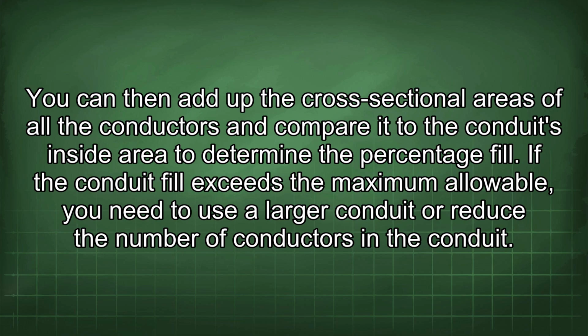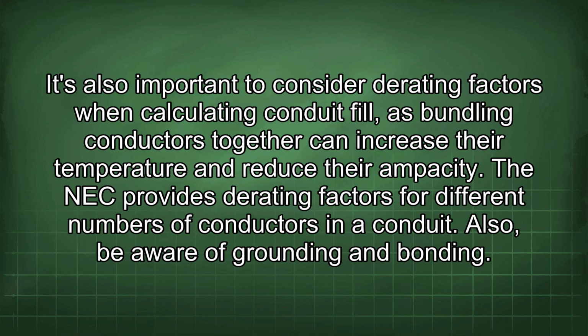If the conduit fill exceeds the maximum allowable, you need to use a larger conduit or reduce the number of conductors in the conduit. It's also important to consider derating factors when calculating conduit fill, as bundling conductors together can increase their temperature and reduce their ampacity. The NEC provides derating factors for different numbers of conductors in a conduit.